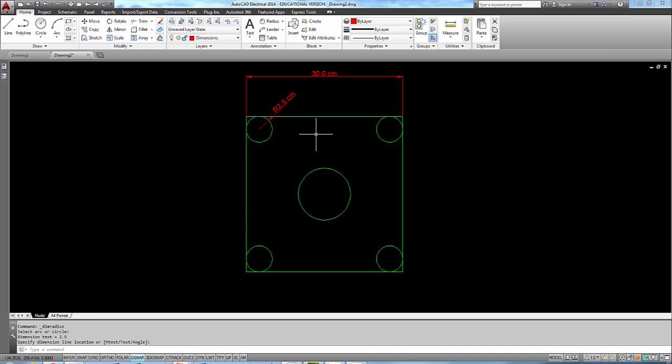And if you want to make them all at the same angle, you can use the copy command again. Copy this, enter, pick it up from the center, pluck another one at the center here. Sometimes the center doesn't appear, so you have to touch the circumference of the circle to make it appear. Okay, and that's good.